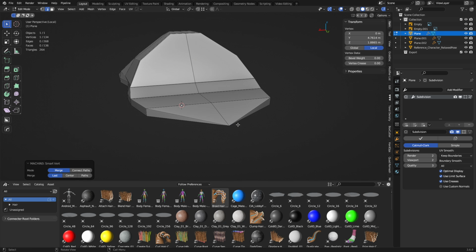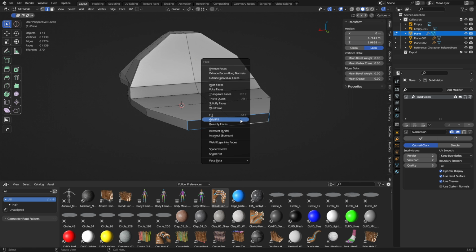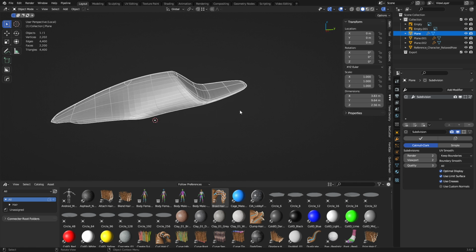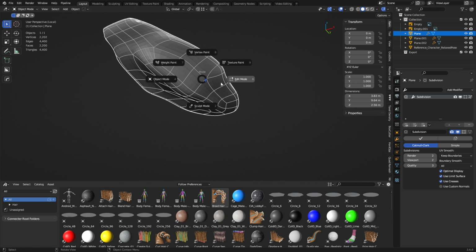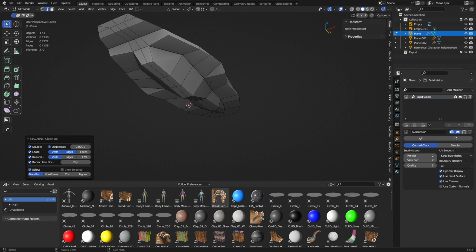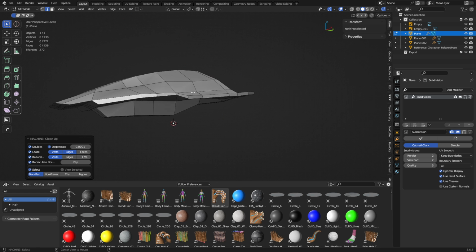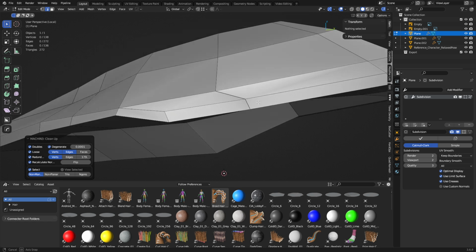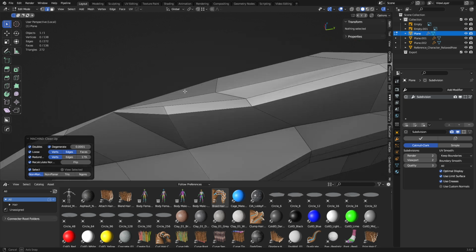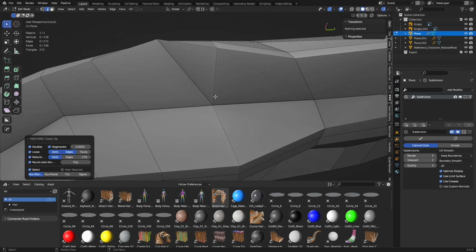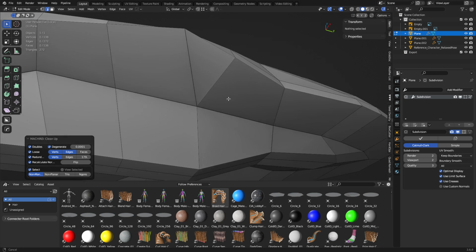So you would take all of this here, and I'll just grid fill that one. This is a manifold mesh. We'll be okay with this. So I just want to make sure there's no errors. Using Machine Tools cleanup feature, I can check it real quick. Look, sometimes it doesn't catch everything. Sometimes you got to find the additional issues and try to work them out.